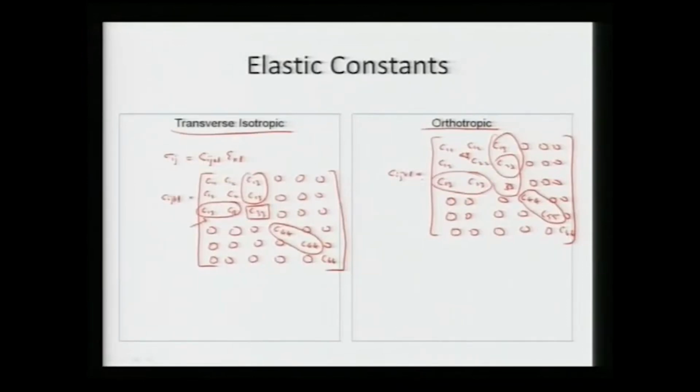So if we apply a certain strain in one direction, it will also have a certain dependence, like it will also alter the strain, the compliance, in the third direction. So strain in 3 is affected, which is similar to strain in 2 and getting stress in 2 and strain in 3, but that does not arise when the system is orthotropic in nature.